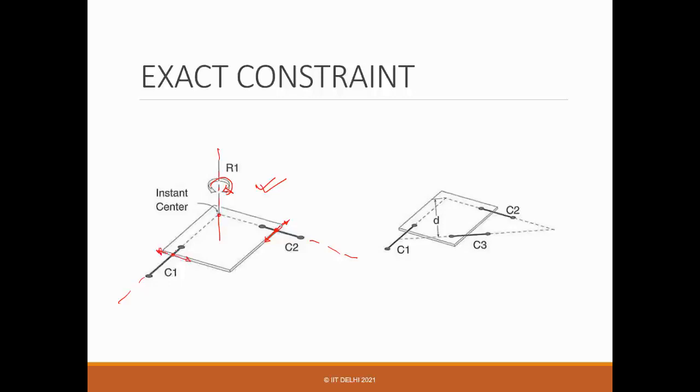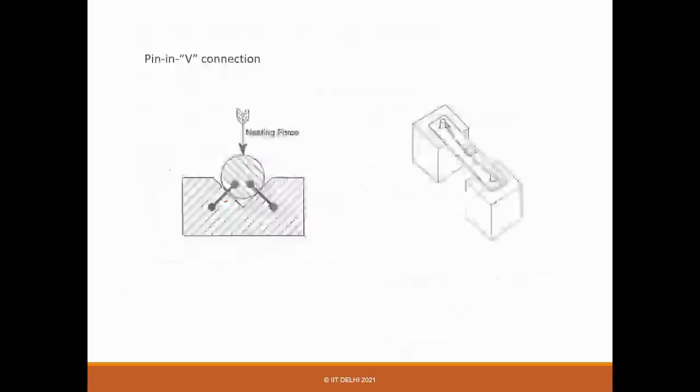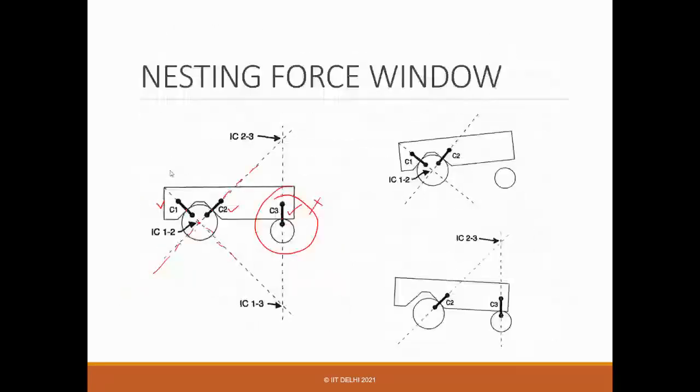So if you try to rotate along this axis, this point will try to move along these directions, which is possible instantaneously. So what we are talking about is instantaneous motion. And that's the reason we say that it has one rotational degree of freedom. And we can say that this is also your instantaneous center of rotation.